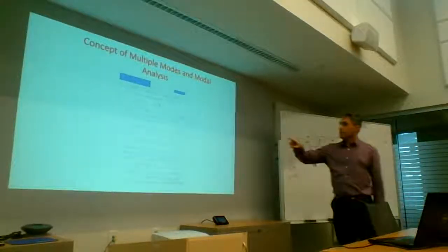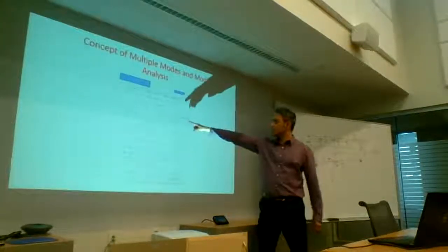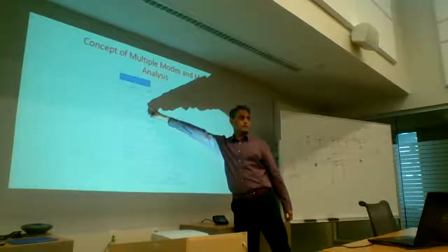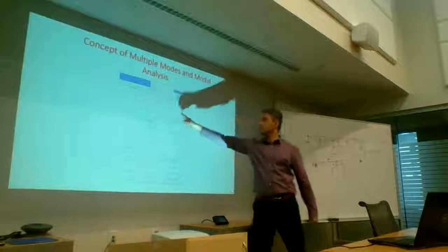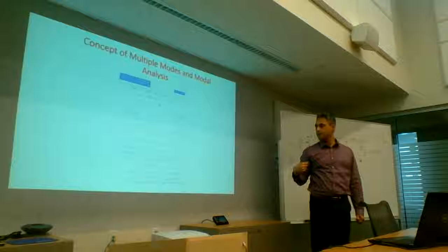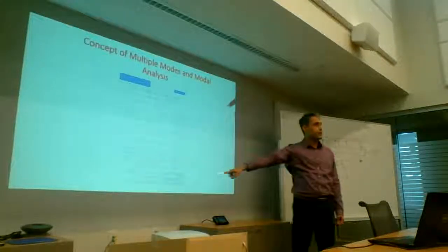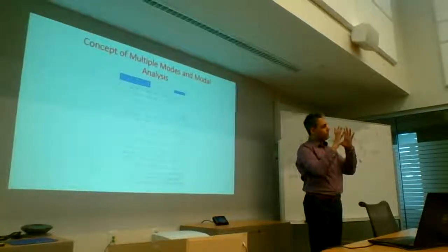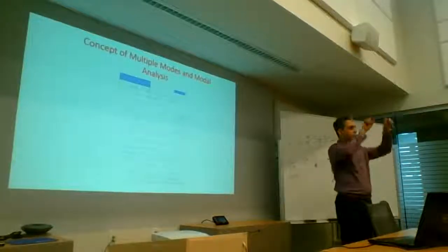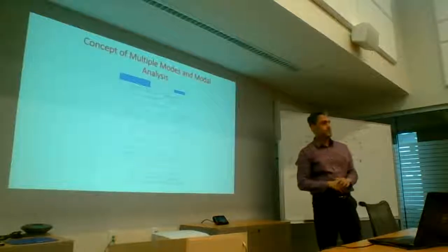They all get, because what happens is when you have the phi n, so you see this K, that's equal to 0, right? So any off-diagonal terms are 0 for both mass and the K, and the same thing happens with the C. Is this K the original K or is it the modified K somehow? Is it the original stiffness? No, this K is going to be different. It's going to be capturing the equivalent stiffness for each one of those single degree of freedom systems. Because the original K is just a large matrix. This will be one number. Yes, that's a good question.